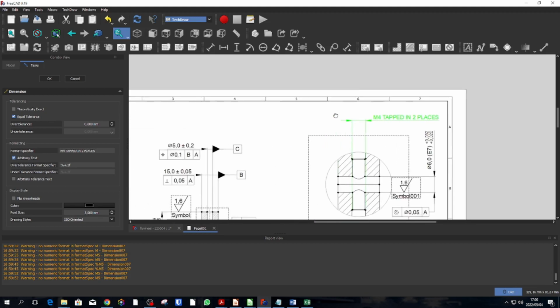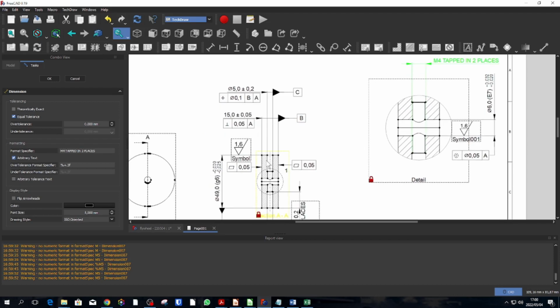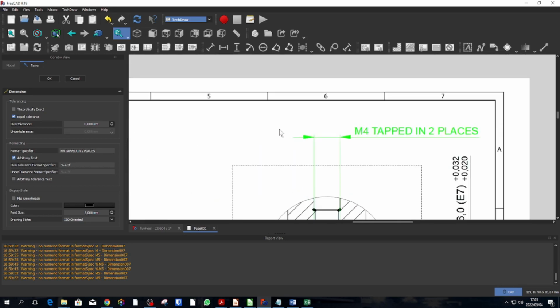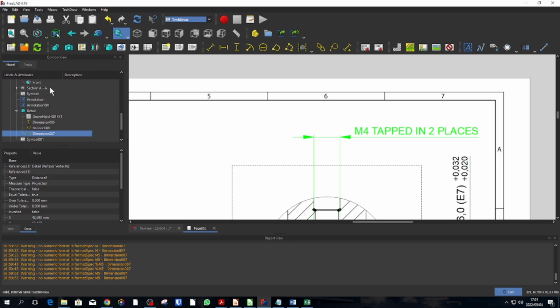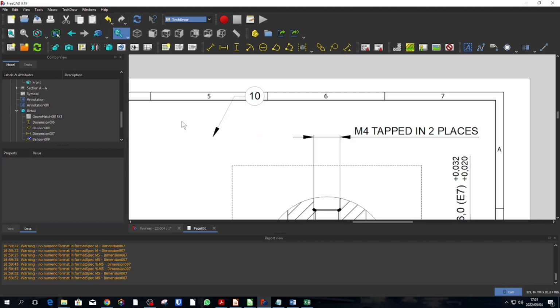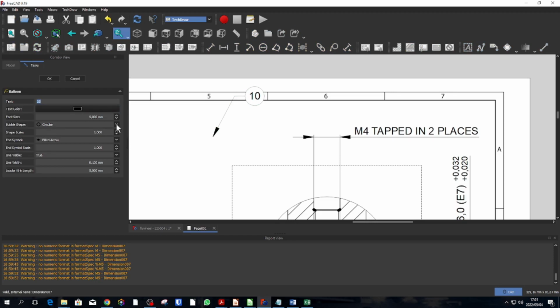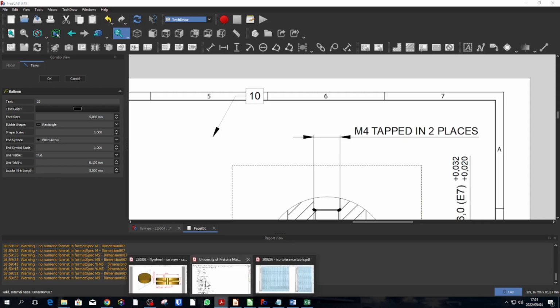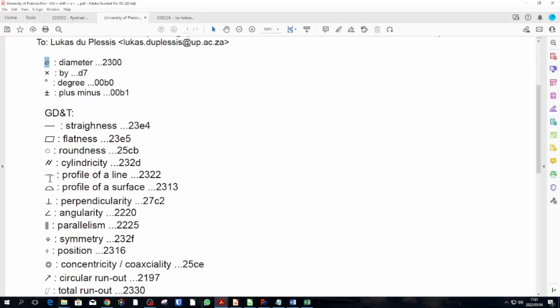Okay. Okay, if you remember, datum C is that hole over there. Okay, so let's do that quickly. So we can okay that. Select this. We create a balloon. Double click the balloon. We make it a rectangle. We go to our. We want concentric or coaxial actually. Coaxial.